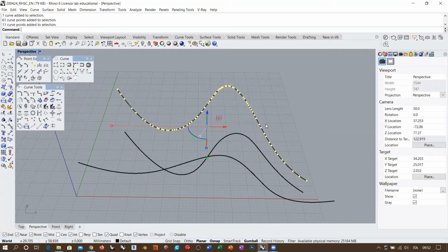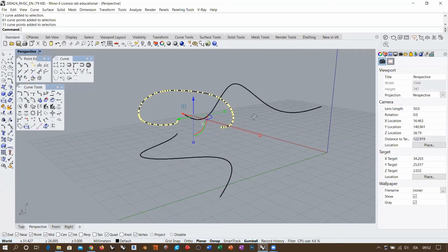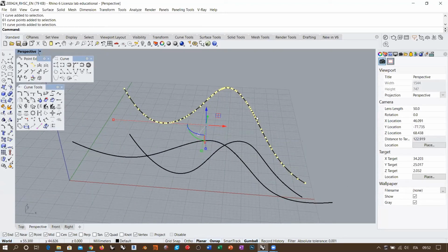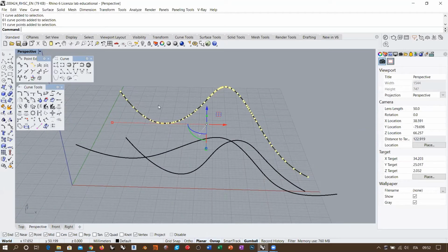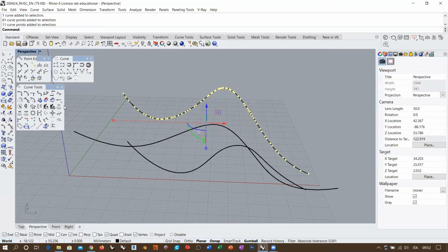But you see that in this case, the curve is smooth enough. The amount of control points depends mostly on the fact that this curve must lie on two surfaces at the same time, okay? So this is the problem here. So can I work with this curve? No, absolutely not. So even in this case, I want to rebuild it. Now, let's make an intelligent use of rebuild in this case. Okay, so I rebuild this one.